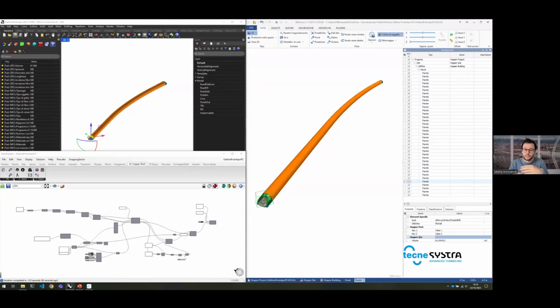The last thing we will show, again in the demo section that will start shortly, is when we have this 3D model in Rhino, we want to create an IFC model out of it. So to do that, we developed a couple of components that use IfcOpenShell that take the mesh, that convert the geometries to mesh, take the properties that are saved in the Rhino file or that you can input directly in the Grasshopper canvas, and write a custom, native IFC file where we can control all the parameters, the hierarchy of the file, and psets and QTOs that you may need.